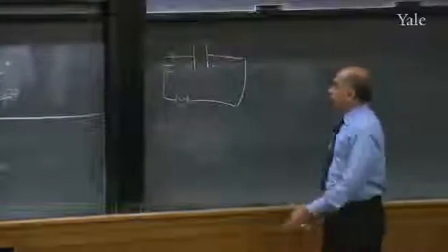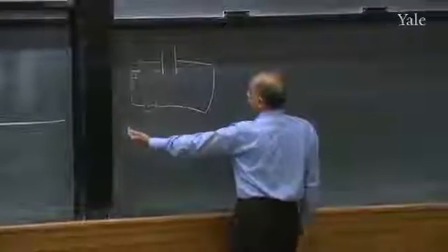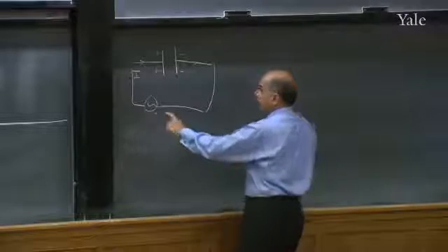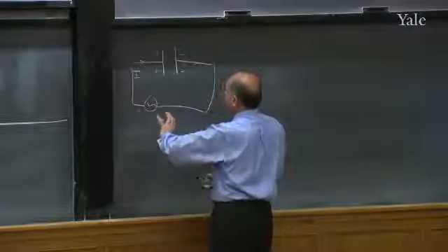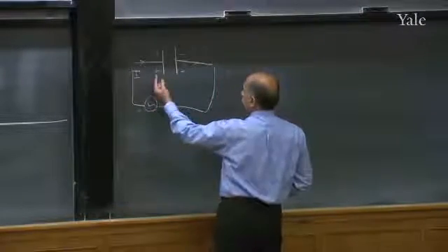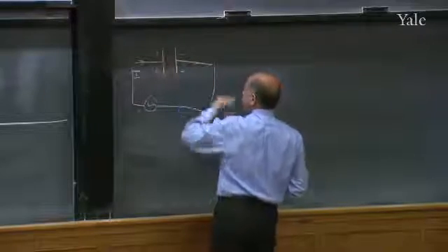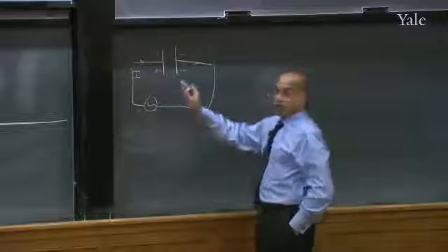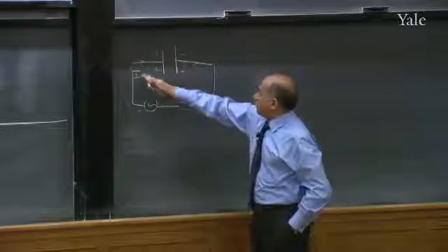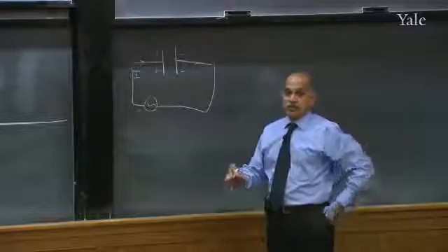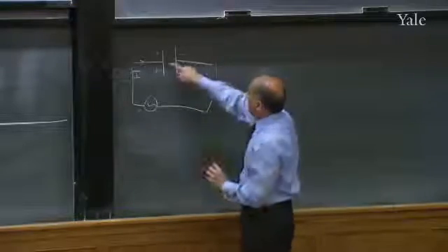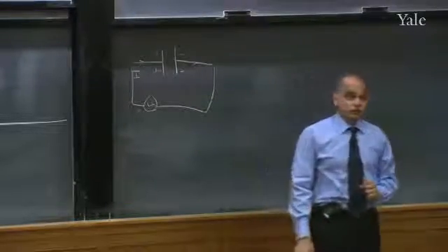It's not possible. What happens is, for a while, plus charges rush here and minus charges rush to the other plate, because that's the polarity of my AC source. Later on, it's reversed. Then minus charges go here and plus charges go there. So there is an alternating current in the circuit, but there is no current flowing right through in one sense. But there's nothing to keep it from going this way and that way, because they don't have to jump the gap to do that.